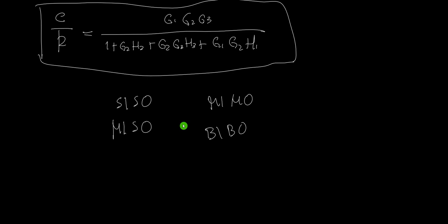Then repeat that process for all the inputs. You remove that input, you bring back another input. Then solve for C, or call it C2, and so on. So if there are 4 inputs, you do it 4 times. C1, C2, C3, and C4. Then after that, the total output will be just equal to the sum or the net of the different effects of different sources or inputs. So you just add them all, C1 plus C2 plus C3 plus C4.